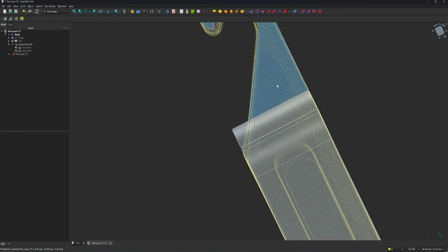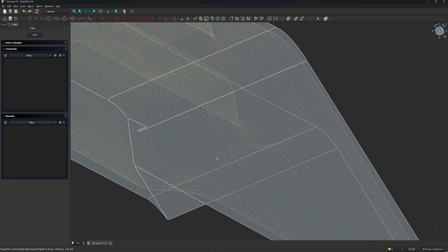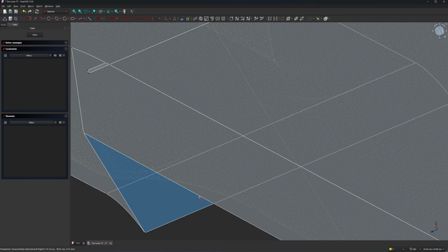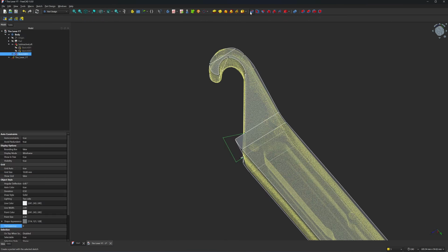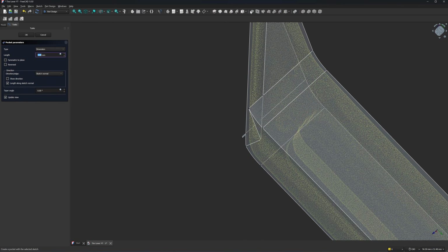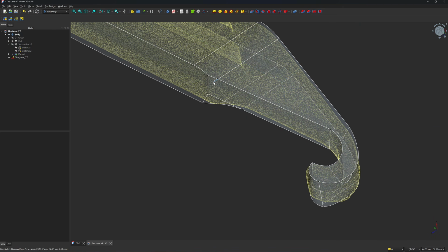Okay, next I'm going to remove this small triangle. Click on this plane. Click on sketch, external geometry. I'm going to create external geometry. I'm using this line, then I should be able to cut this pocket, close, pocket, reverse. So I cut this one out, click on OK. So we have a small one here.